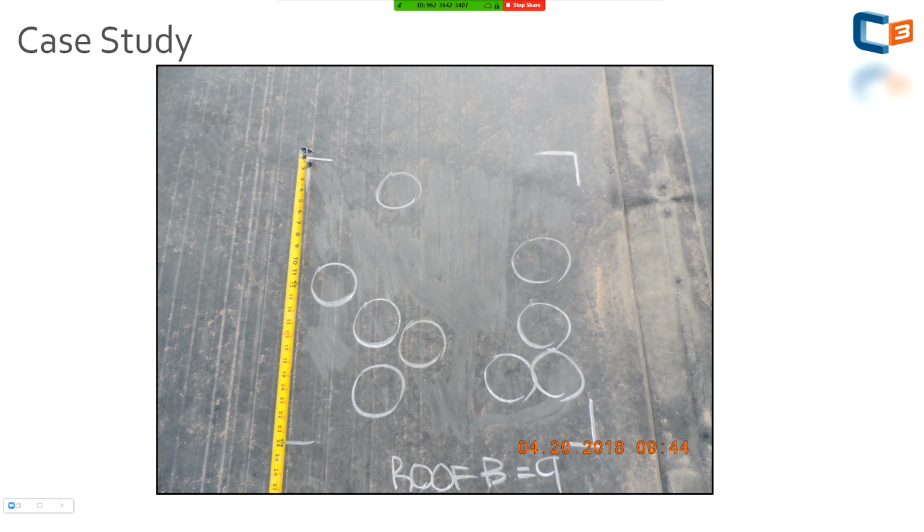This is something that you're going to see on the defect side. You're going to see installation defects in products that were just installed incorrectly, and this is a case of that. On this roof, we had 3 roof sections. We had a ballasted, built-up roof, EPDM over fiberboard, which we pursued because it had very good depressions. And then we had this side. This side was about a 10 square area, and it just appeared a little bit different. We thought that we felt depressions.